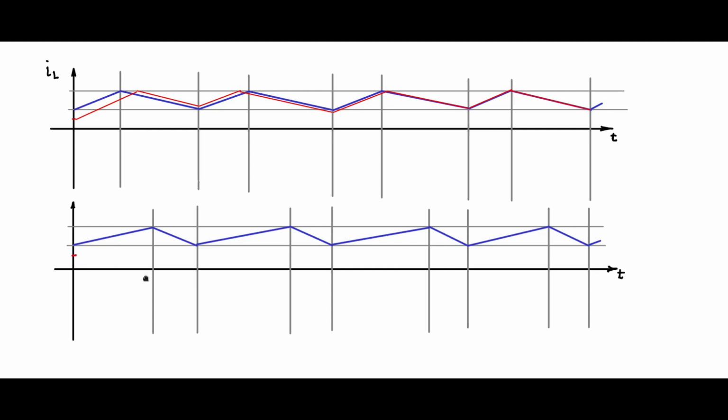So when you introduce a disturbance, from this point onwards it will start going parallel to this line. It will have the same inductor slope. So let us say it takes this line, it hits the top value here, that is the IL reference value, then goes down and resets again, because this is the time duration when the Q of the flip-flop is low.